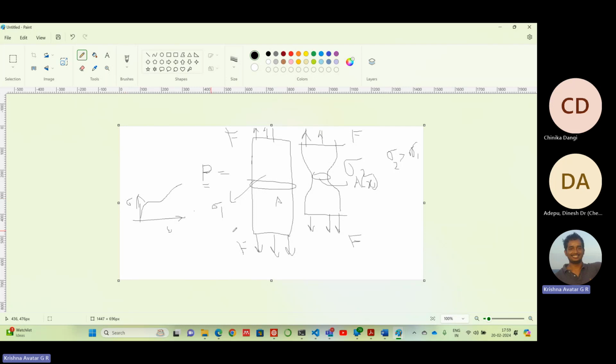In the stress, they don't actually measure the actual stress. They keep the same area still. They consider it as if the same area is existing, and they just do F by A. They keep on varying F, and A will remain the same as A naught.